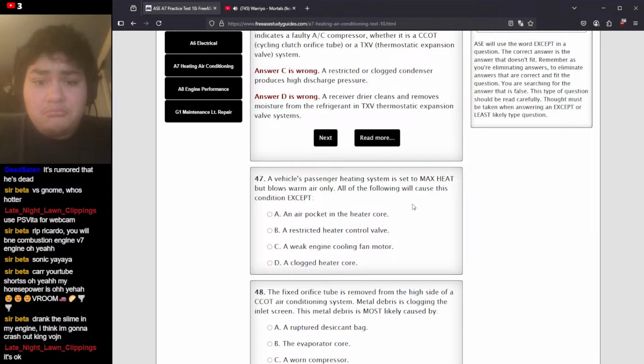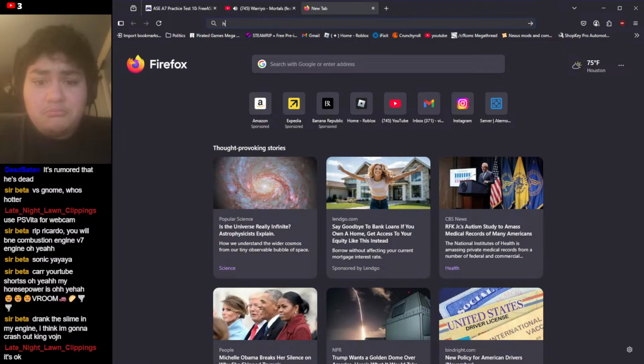And the job of coolant is to transfer that heat from the engine and put it into the radiator, so that the radiator radiates the heat and cools the coolant, and the cycle continues. There is coolant that goes from the engine to a second tiny mini radiator, and it's called a heater core.